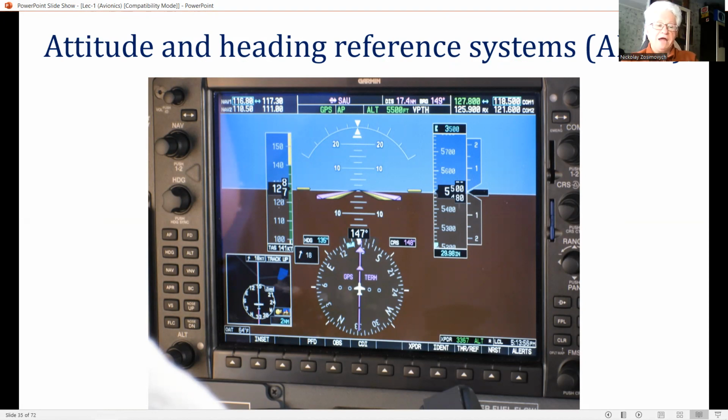The use of very high accuracy gyros and accelerometers to measure the aircraft motion enables an inertial navigation system, INS, to be mechanized, which provides very accurate attitude and heading information together with the aircraft velocity and position data, like ground speed, track angle, and latitude and longitude coordinates.